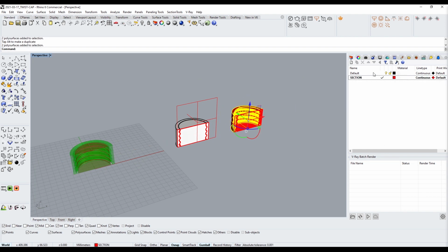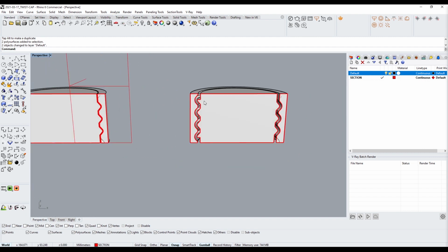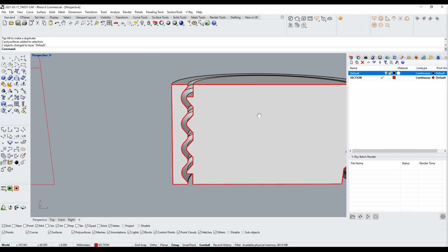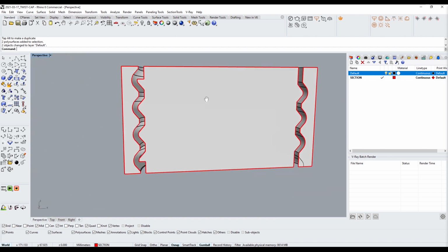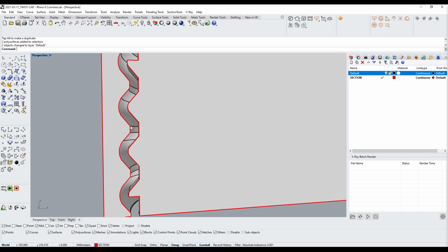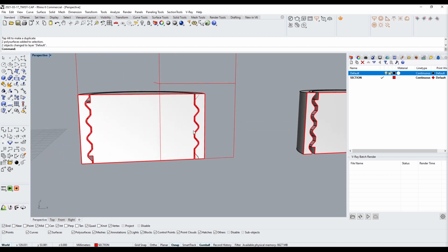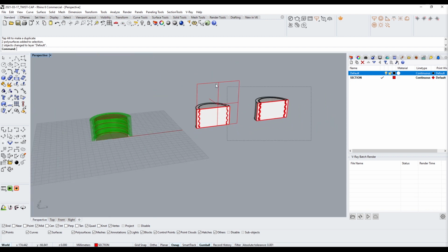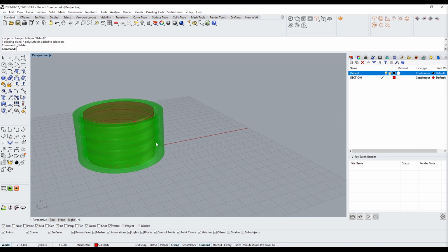And I'll change the object layer here. As you can see, when it has 1 millimeter, it's way wider. It'll still work, don't get me wrong. The important thing is going to be the threshold between how tall this one gets and the gap. So if the gap is the same as the twist height, that's where it becomes an issue. For the most part, 0.3 has worked, 0.5 will also work. But now let's go back to the model here.